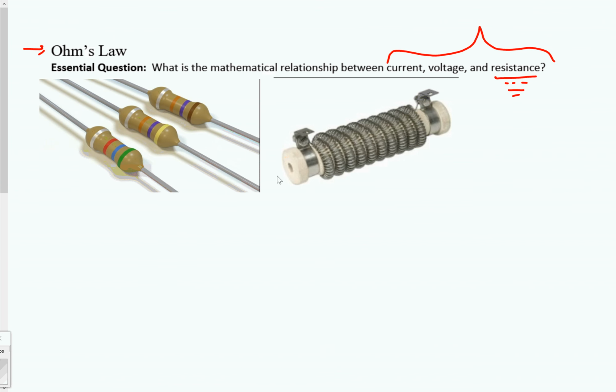No joke, just the other day I had some little neon bulbs that I was playing with, and you will blow those bulbs easy if you hit them with much voltage. So I was taking a resistor, a little component that looked like this. We use this little squiggly line symbol to represent it, but I was using a 100 kilo ohm resistor in series.